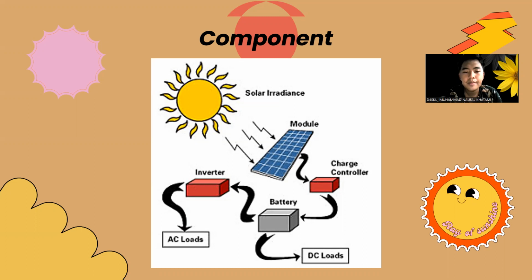The solar cell module produces electrical energy that is proportional to the surface of the panel exposed to sunlight. The battery charging controller circuit in the solar cell system is an electronic circuit that regulates the battery charging process. This controller adjusts the battery voltage within 12 volts plus or minus 10%.